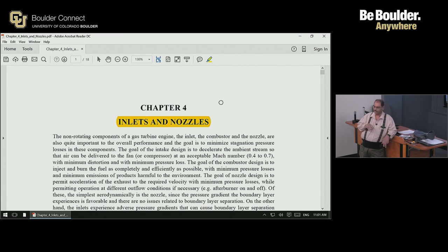So especially the compressor. Now, as you can imagine, when you're talking about very small clearances of the order of a thousandth of an inch or something like that, any distortion of the casing or the deflection of the shaft can cause the blades to touch the casing.